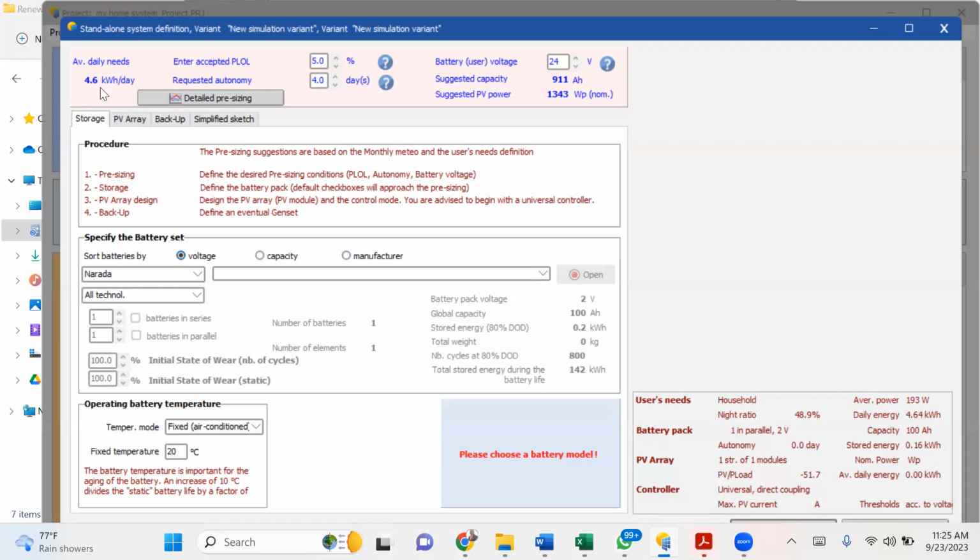It's normal. What do you increase the fan to? 2 hours. I increased it to 2 hours. And I increase TV to 12 hours. And I increase my lighting to 12 hours. So I upgraded the load. So it's no longer 3.4. Rather, it's now 4.6. It's still okay. It's still below 5 kilowatts. I don't think anybody in this class will use more than 5 kilowatts.